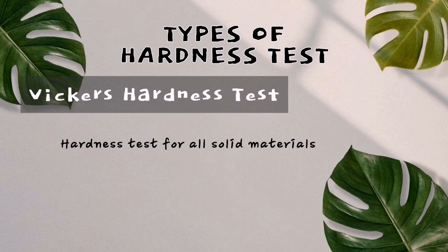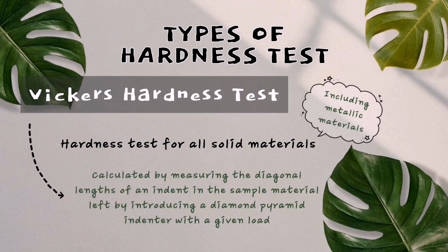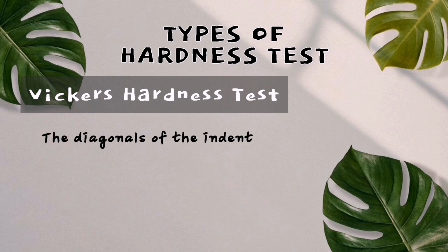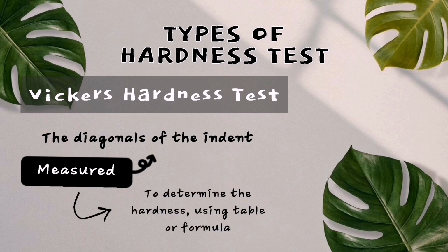Vickers is a hardness test for all solid materials, including metallic materials. The Vickers hardness is calculated by measuring the diagonal lengths of an indent left in the sample material by a diamond pyramid indenter with a given load. The diagonals of the indent are measured optically in order to determine the hardness using a table or formula.